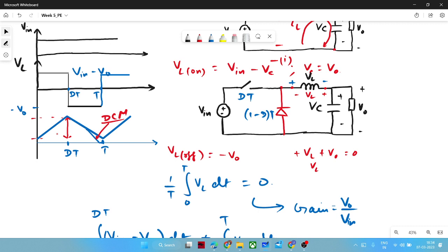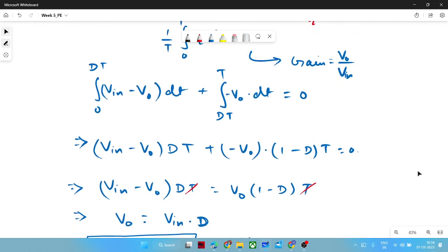What I mean by proper inductor is the required value of inductor to reduce the level of ripple current up to your desirable level. So whatever value of ripple current you want, according to that you will have to compute the value, and then you will get the parameter of the inductor, and that you have to connect in the circuit.